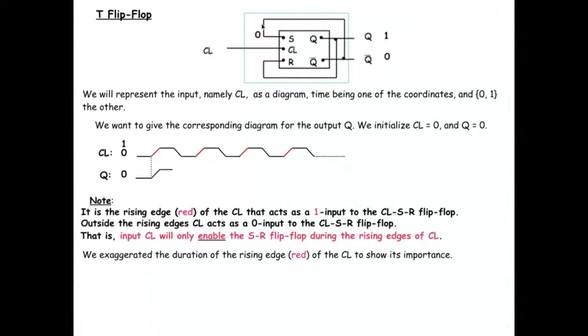Now, that means that S will become 0, right? And you think, oh, then now it should change back. Why will it not change back immediately? Why will this flip-flop not? Yes. Because the clock needs to be 1 for it to change again. That's right. So that 0 will sit there at S, but it will not actually change anything until clock is 1 again.